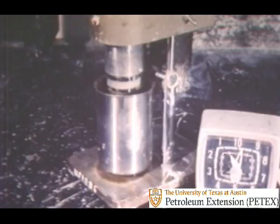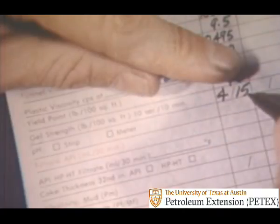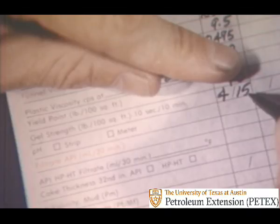The second gel strength measurement is the 10-minute gel strength. To determine it, restir the mud at 600 RPM for 10 seconds, then shut off the viscometer and let the mud sit still for 10 minutes. The 10-minute wait gives the mud a chance to gel, and the test reveals the amount of force needed to start the gelled mud flowing. After the 10-minute wait, turn the hand wheel counterclockwise and obtain the maximum dial reading. The 10-minute gel strength is also in terms of pounds per 100 square feet. Here it is 15 pounds per 100 square feet.